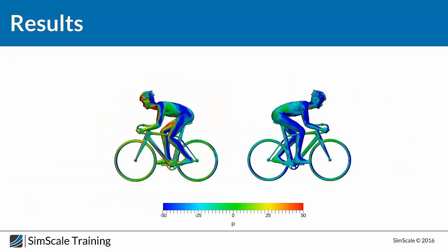So here we will now show the effect of the side wind on the pressure. On the left side, we can see the side where the flow is hitting the bike, where there is a component of the flow velocity from this side, and the right-hand side is the wake region. For the thin tire, we can't see a really significant difference of pressure.